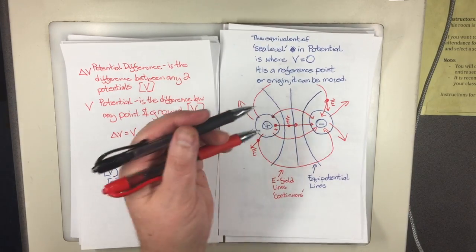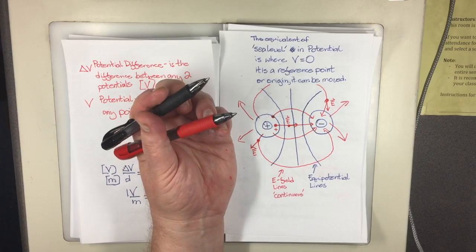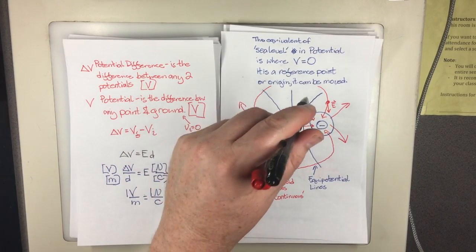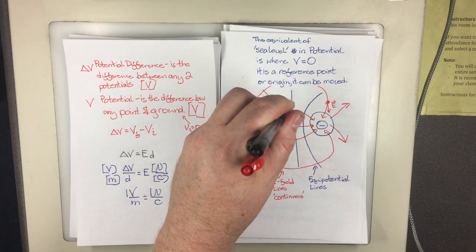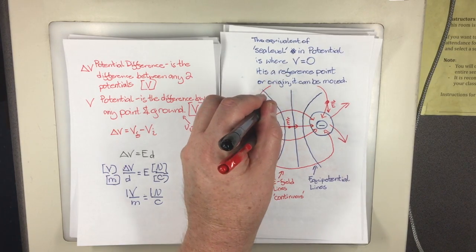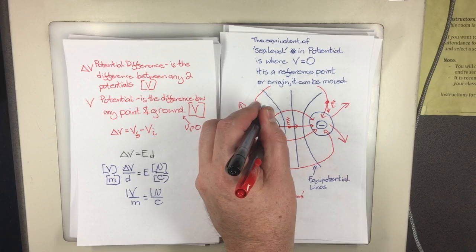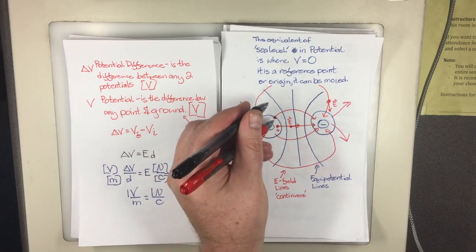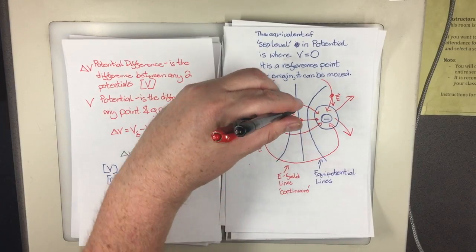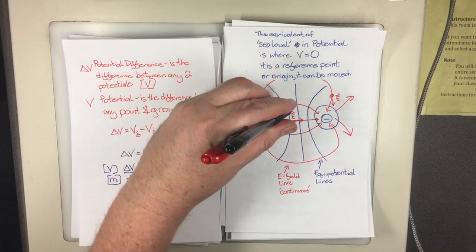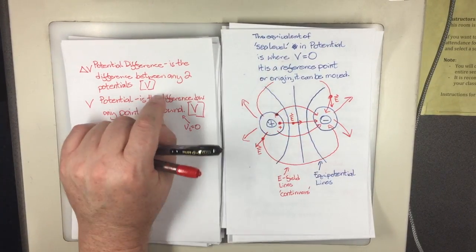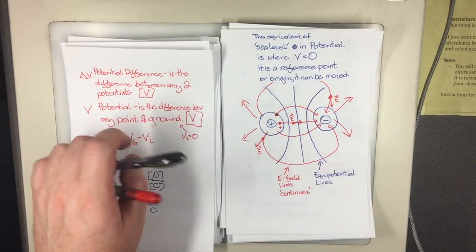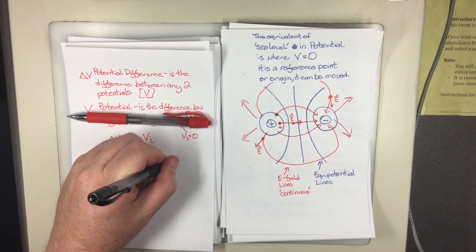So the red pin is the red lead and the black lead is the black pin. Put your red pin closest to the red port, and then you're going to rotate around. What's going to happen is that your digital multimeter is going to give you a number, and you rotate